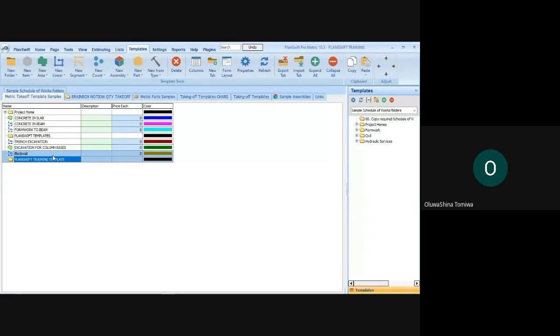There we are going to do site clearance. We are going to do topsoil excavation. We are going to do disposal. We are going to do trench excavation. We are going to do concrete in foundation. We are going to do level and compacting. We are going to do earthwork support if necessary.